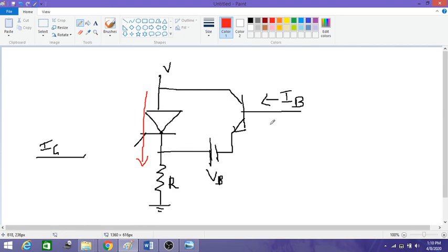There is a voltage source connected to a transistor. Once I give the base current, the transistor is on, and this voltage source is switched in. Then a large voltage is applied in the opposite direction for a small amount of time. The current flowing through this SCR is then cancelled, and the SCR comes to a halt, or turns off.